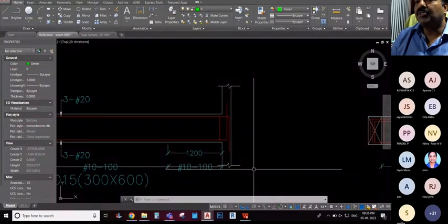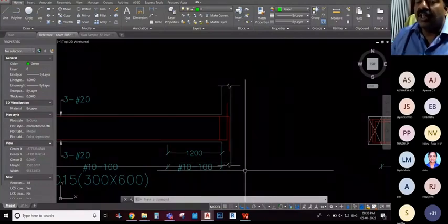And suppose, think of one particular site, it's a 20-story building, and one side is a big column. You please consider, you have enough space, you don't have to bend it. But if you don't know that rule, you will think that in all places you have to bend. So 3 bars you are going to bend unnecessarily. That is 3 bars, just one mistake.